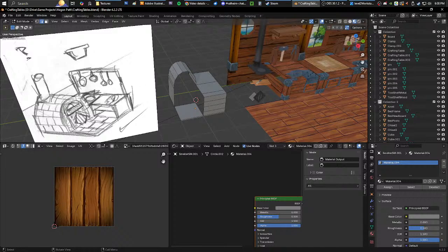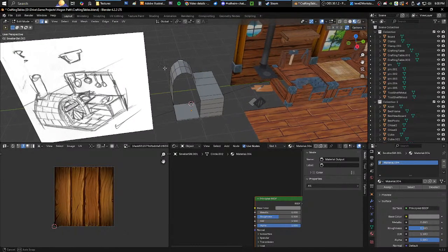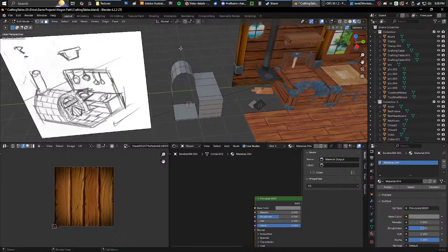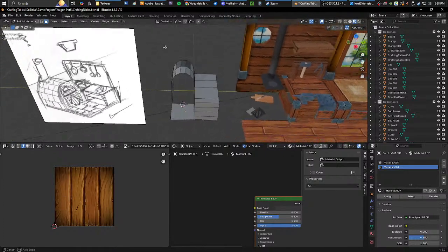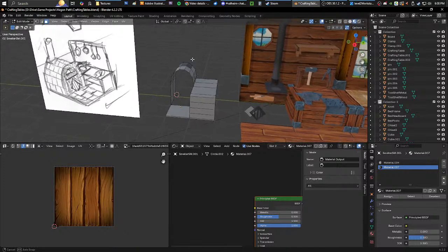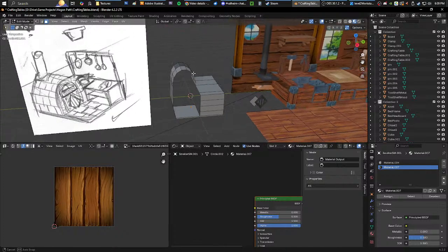So I'll need to cut right here, because I'm going to texture that a different color. So I'll need to go ahead and put one edge loop in there. I'll just make it right down the middle. That way, these faces here, 1, 2, 3, are in a different material. So I'll go ahead and color them a different color now. I'll make a new material, and then I'll make that one a little bit darker. And then I'm going to assign. There, just like that. So that assigns the color to those faces. The same with this, the same with this side.